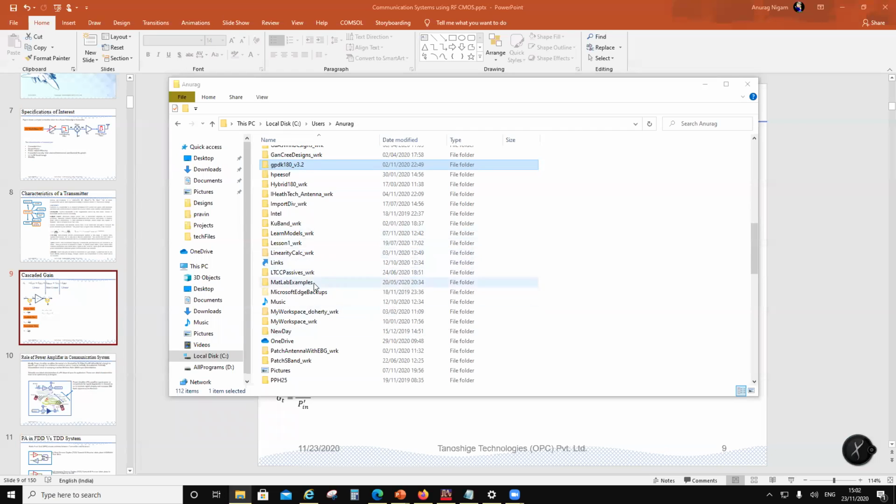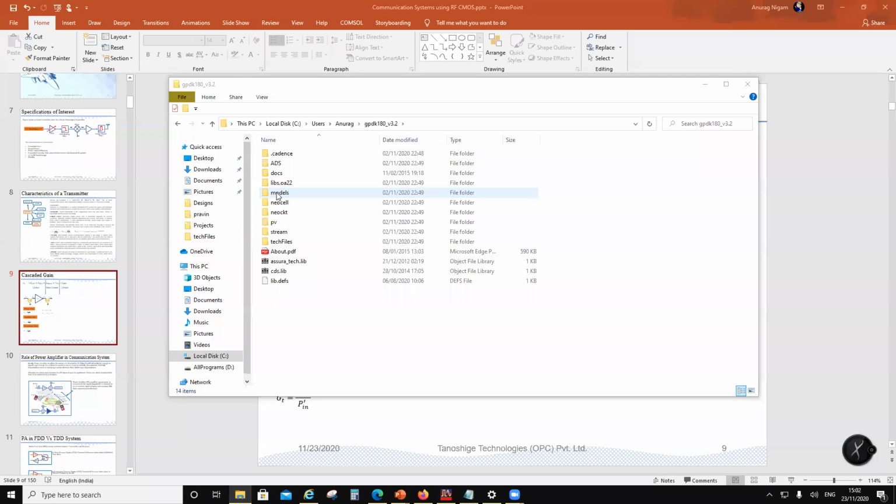Okay, welcome everyone back. There's a question: people want the GPDK. I would give it to you, but let me add a word of caution. The word of caution is the following: only in the PDK, only NMOS 1 and PMOS 1 are modified. So basically, all other models are not.